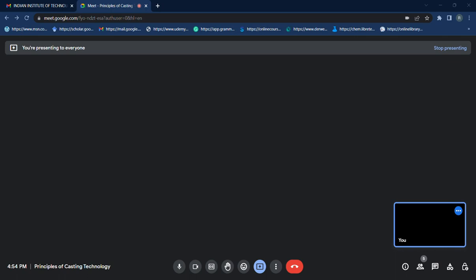Okay, and then for the economical removal of the risers, breaker cores can be used between the riser and the casting. Breaker cores are typically made of bonded sand or fused ceramic material. And further, by keeping the mass of the breaker core small, the breaker core quickly reaches the temperature of the surrounding metal and does not appreciably affect the solidification of the riser.